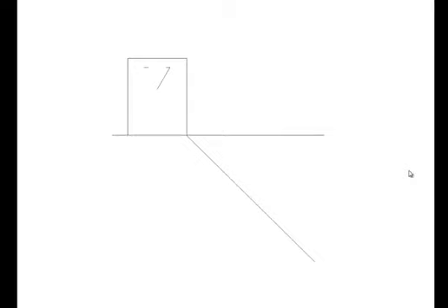We now draw in the prism in elevation. After creating the prism in the elevation, we will project across our height from the elevation to the end view. Also, we will project down our lines from the elevation to the plan. The line from elevation to the end view is going to give us our height line for the end view.